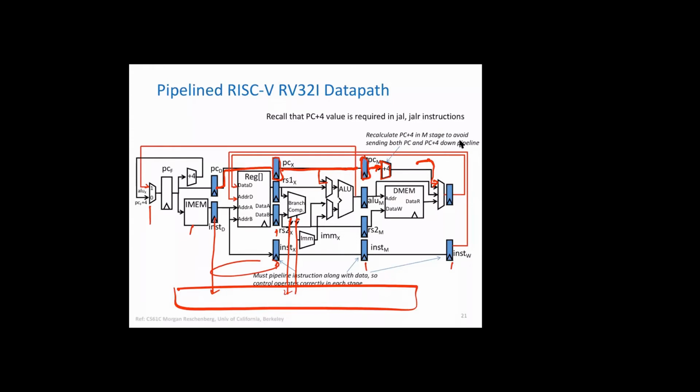Now you generate these signals here when the first instruction is getting executed, or the instruction is fetched and then it comes to this place. But these are used in different clock ticks, right? These are getting used in all these clocks. For example, if we are writing it back, that is in the fifth stage, the corresponding thing should be here.